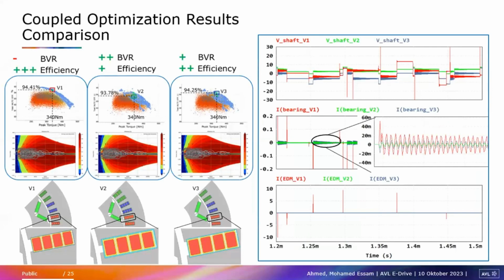Yes, we were doing some simulation on the insulation, for example, checking partial discharges using the same methodology. Unfortunately, we could not quantify a limit for the partial discharge within GMAG, because at the end, after the integration of everything in the stator, you do end-of-line tests, including, for example, the high potential voltage test, surge test or turn-to-turn test. And then you measure, for example, the leakage current.